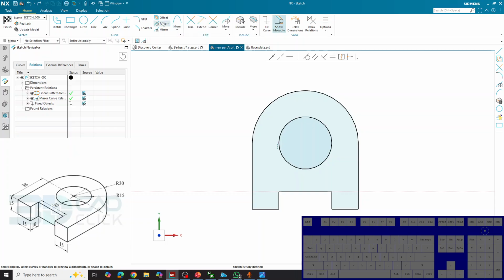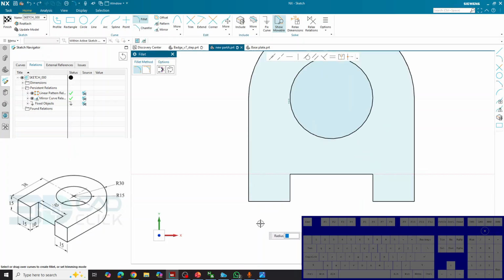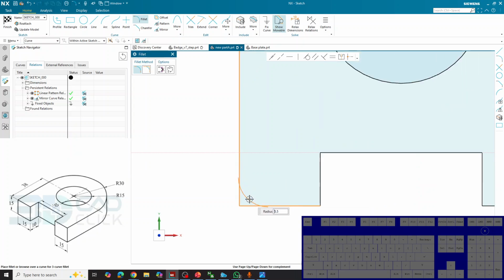So I've shown you the offset tool, the pattern tool, the mirror tool, and oh, let's show you the fillet. Okay, the fillet basically what it does is that it takes an edge, so it doesn't have to be like a 90-degree edge, by the way. It can take 2 edges, 2 lines, and you can basically make the corner smooth. Okay, and based on the number being bigger, you can get more curvature. So I'll pick something like 2, like that. Okay, click here, there, type 2. There's your fillet.